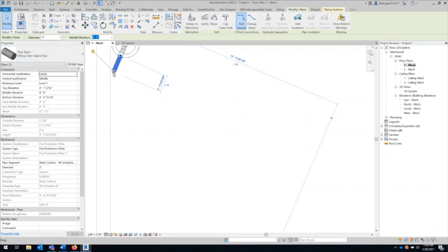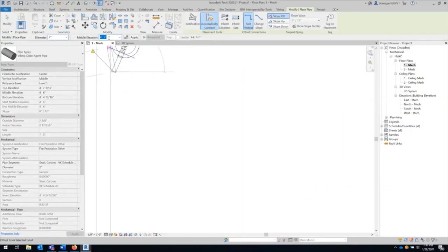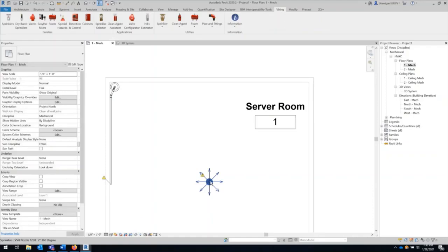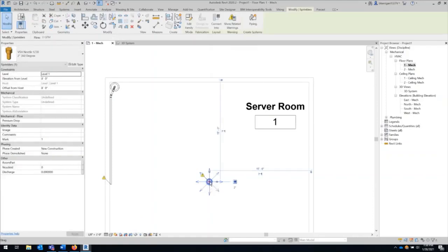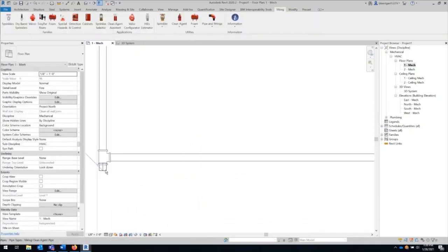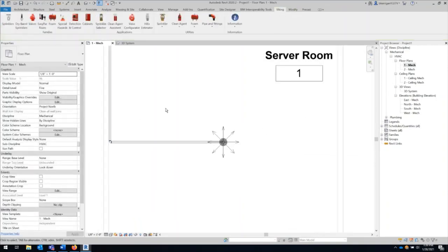So one of the easiest things to do is just draw right off the end of that little piece of pipe we created there. So with a 9-foot ceiling and a nozzle at about 8 feet, we probably want to run up to maybe 8 foot 10 inches. And then we'll just run down to the intersection here with the nozzle. And then when we're looking at the nozzle down here, we can also just draw from the nozzle straight up to that 8 foot 10 and bring it out to meet up with our pipe over here. Looks like I overran a little, so you just delete the little extra section, turn that back into an elbow, and you're good to go.